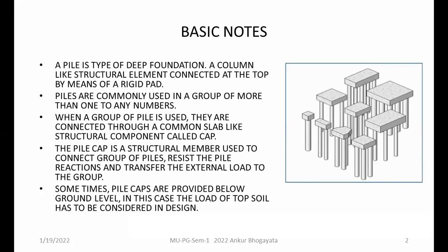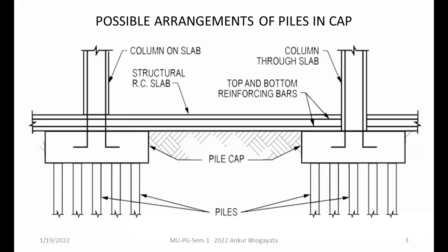So sometimes pile caps are provided below the ground level also. In that case, topsoil has to be considered as loading itself. So depending upon the actual condition, you should take into consideration the forces. So that's a pictorial view, an illustrative view of the pile cap itself.